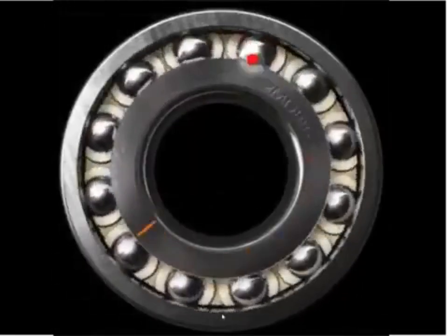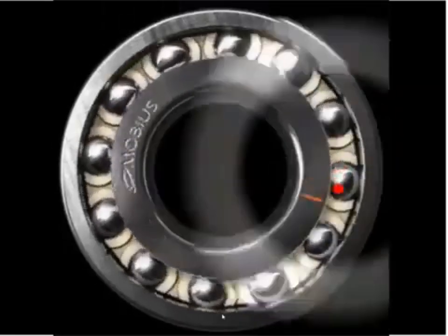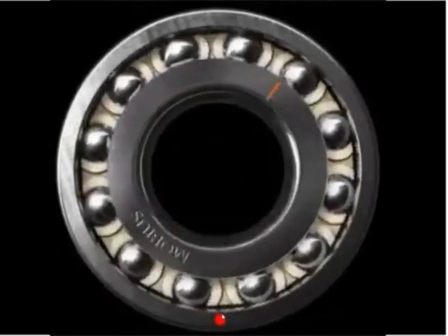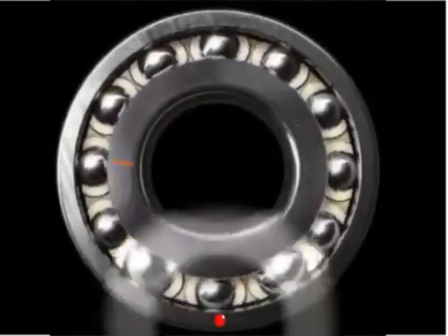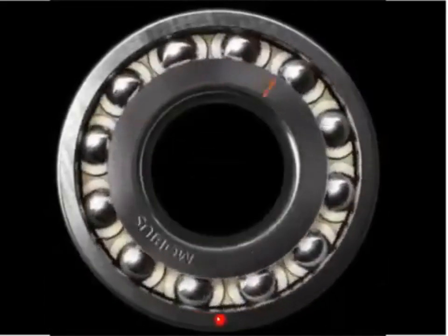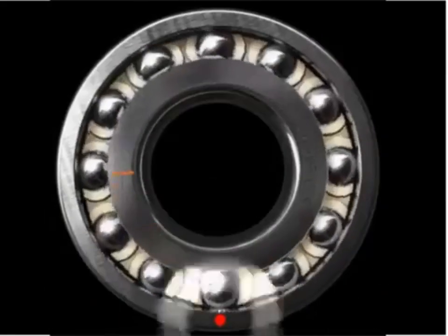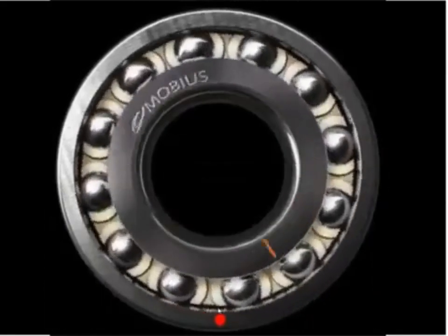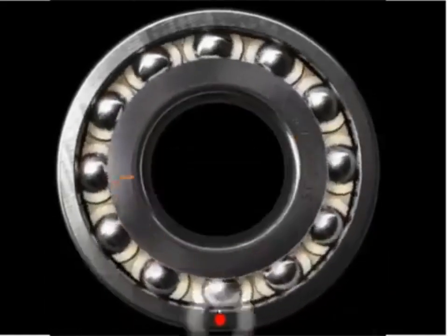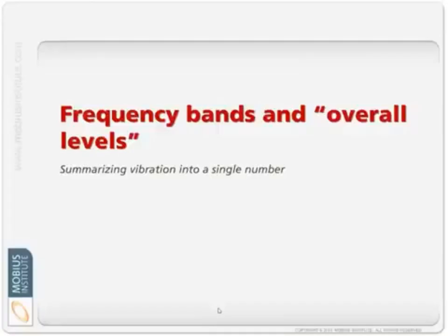And hey, if you've got big, expensive bearings, people have been known to actually just rotate the outer race to take that damaged area out of the load zone, because it's quite common to have failures down in this area because it's under so much load for a horizontally oriented machine. Anyway, moving along. So we can use that information and detect faults quite early.